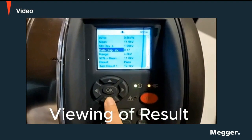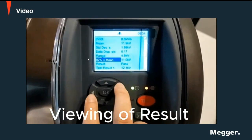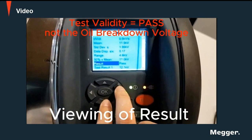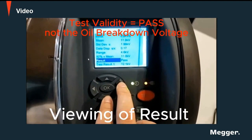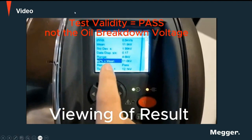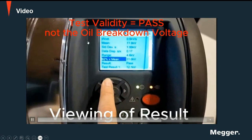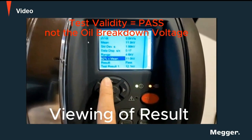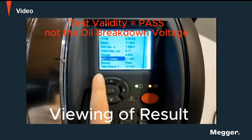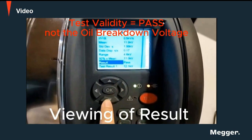That is the 92%. So remember our criteria for testing validity. If it is more than 92%, the testing has failed and you need to test again. So here, the test validity is passed. But again, we are not referring to the oil breakdown voltage. Later on, using this mean value, the 11.9 kV, the value of the mean voltage, we will use that to check against the limits according to the standards.